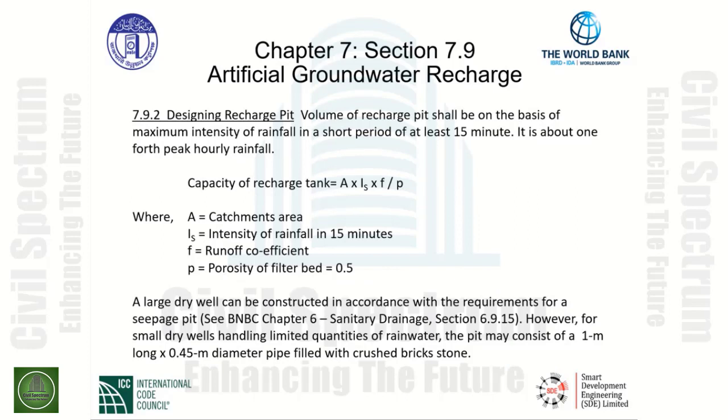Designing recharge pit. Section 7.9.2. Volume of recharge pit shall be on the basis of maximum intensity of rainfall in a short period of at least 15 minutes. It's about 1/4 peak hourly rainfall. Capacity of recharge tank is given as a capacity equating to